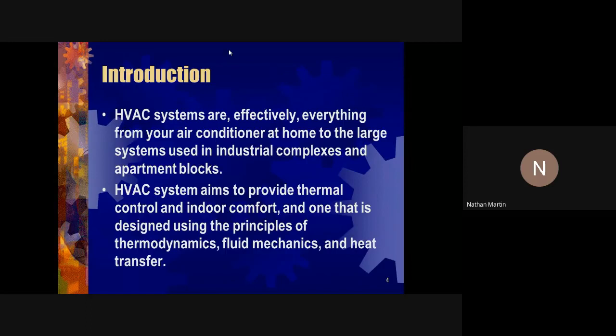So efficiency is key, and when it's not running efficiently, guys, it will burn more energy. If you have a unit that needs servicing and you don't service it, it will burn more energy because it takes more to cool the room. The filters are blocked, and then the AC starts to struggle to cool the facility.